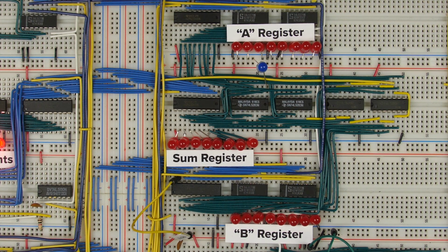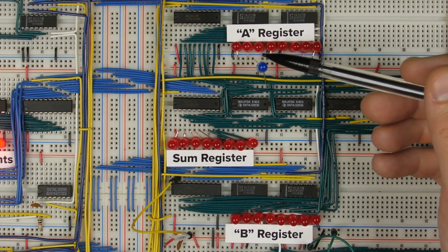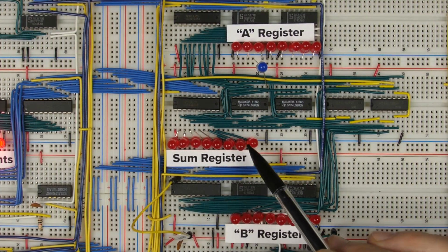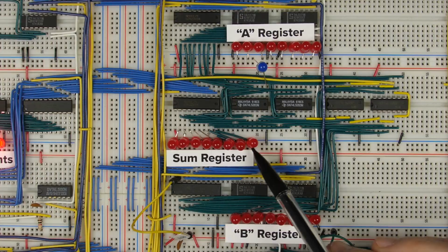Well, unfortunately, we don't have a single bit sitting around that just tells us whether the result is 0, like we did with the carry bit. So we need to build some logic. So how do we know if a number is equal to 0? Well, it's going to be equal to 0 if each of the bits is a 0. And so how can we tell if all 8 bits are 0? Well, we could use a NOR gate.